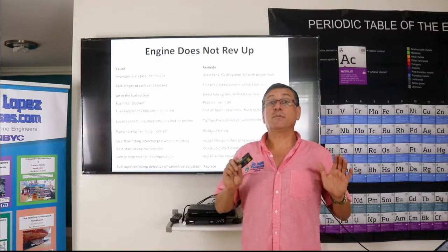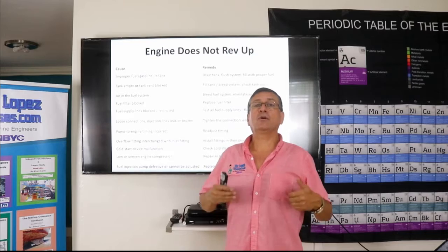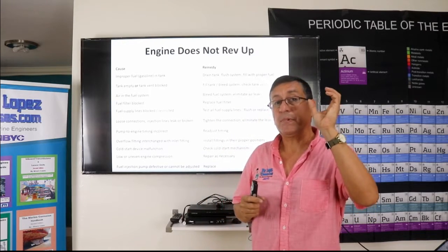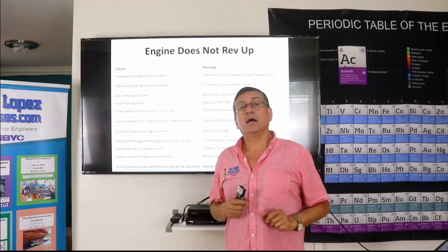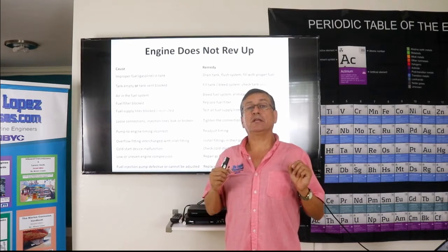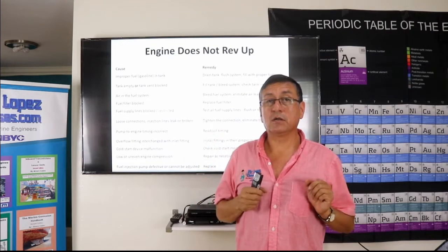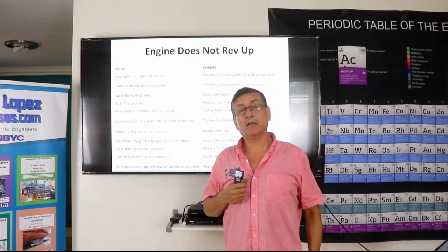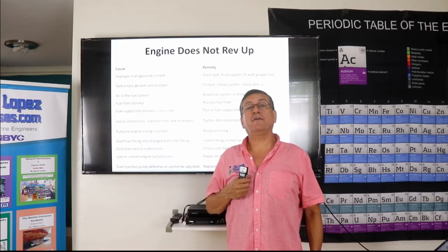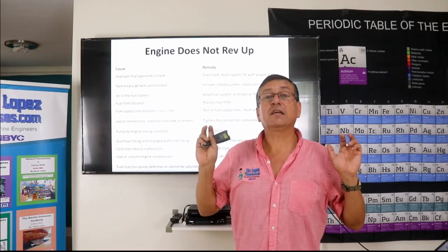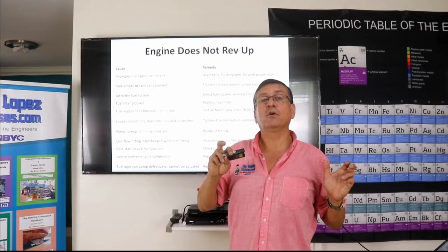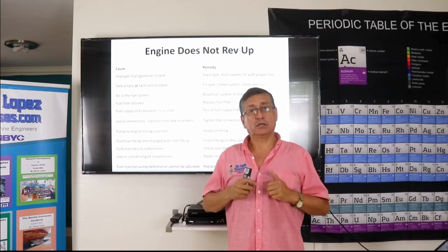That's it. If the problem is in the high pressure side, we are going to concentrate on the pressure on the gauge, on the manifold, and on the pressure regulator located at the end of the common rail, and we are going to check if the injectors receive the signal between 4.5 volts and 5 volts in each injector.